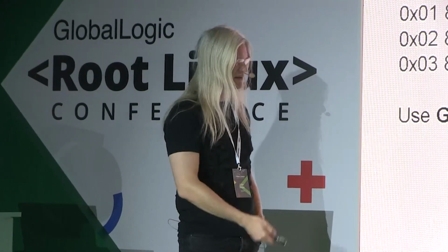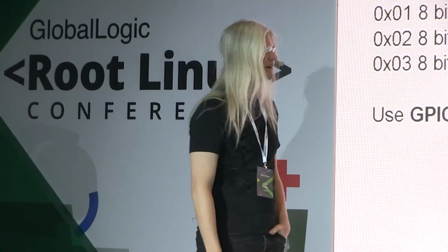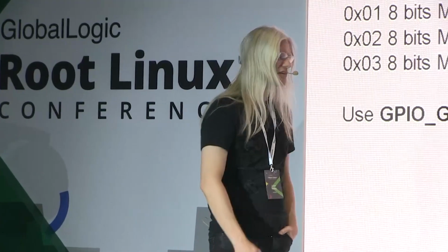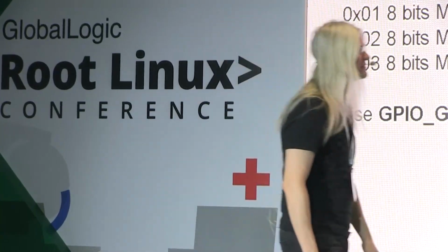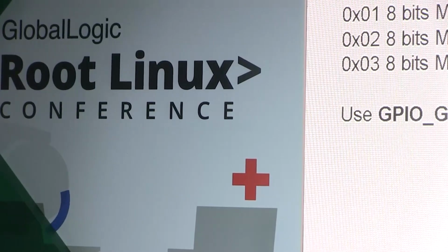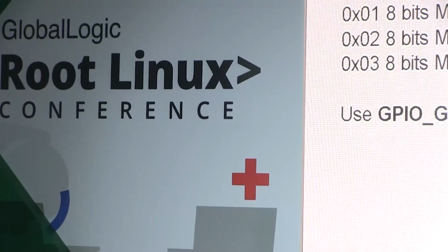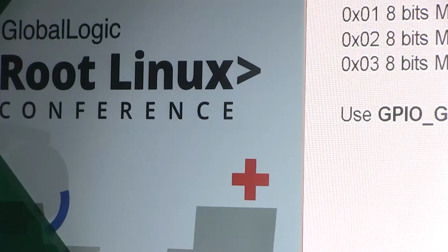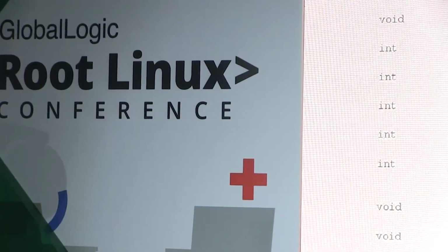So he just disabled some nice things that we would like to have under software control. But that's all right. ASIC engineers do that all the time, especially when they use that I/O cell for something else that is not general purpose input-output, if it's a bus of some kind. For example, if it's I2C, then he will just enable this, because you have to have pull-ups on I2C bus lines, data and clock.